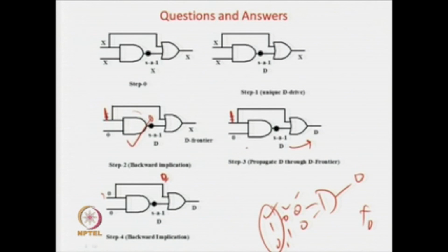So, it was successful here, but now you see it was a 1 because he has not used x. So, there would be an inconsistency because you require a 0 at this, but it is a 1, and you will declare that there is a big problem over here, and that is the circuit fault cannot be tested. Again you have to try out the other options like 0 1 or 0 0, all these options you have to try out. But by keeping an x, all these problems are gone. That is what was the emphasis, that in DAlgorithm you have to keep more x's to keep your options open. That is, you have to defer your inconsistency as much as possible.